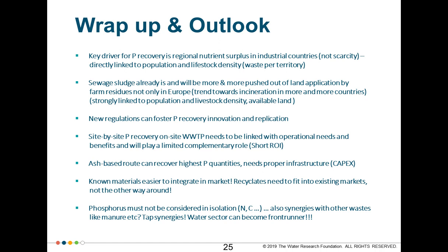The big advantage of separate incineration of sludge is that you really concentrate the phosphorus. Of course, you also concentrate the heavy metals, but there are technologies already out there enabling us to separate the phosphorus and the heavy metals in a very effective way. And then you can produce defined products. If you look at biosolids, it's always a trick to store them in a safe way.